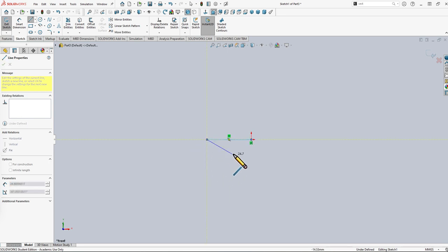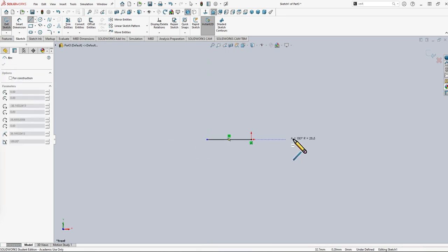As I'm drawing my line here, I'm going to left click to make my line stick into place. And I can see 2 sketch relations already appeared. When I say sketch relations, that's these little green images that appear on my drawing. This one right here, I've already talked about quite a bit. It's the horizontal sketch relation. That's just saying this line that I drew here coincides with the x-axis and that they're both horizontal completely. And then the next one is this little one here in the corner at the x-axis. This one is showing that it is coincident with the origin. So SolidWorks understands that this line is not only horizontal with the x-axis, but that it's touching, or coincident, with the origin.